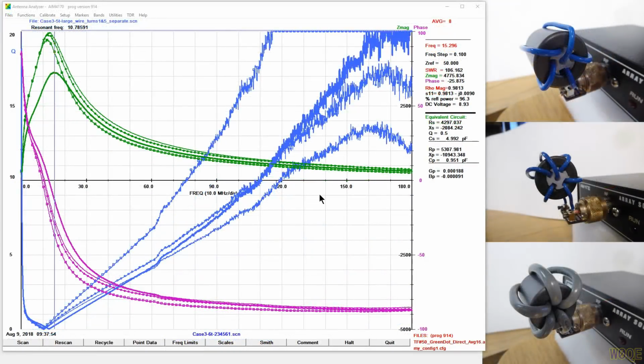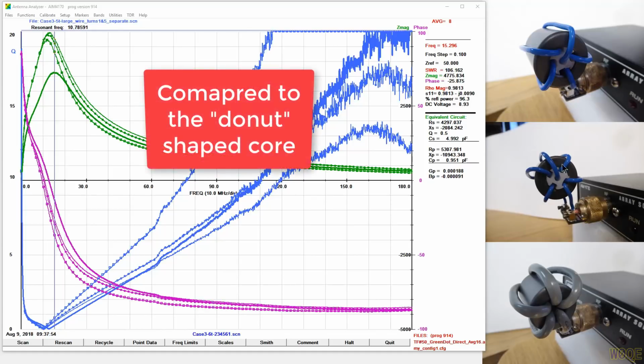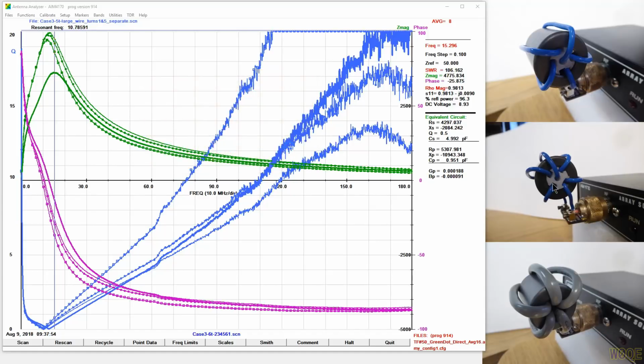And here are shown 4 graphs with beads. The bead typically has a higher effective value to create impedance, but has a smaller opening. And since the opening is smaller, that means the turns are going to be much closer to each other than they would be in a larger core. And I tried to understand whether or not trying to separate the starting turn from the last turn is important or not.